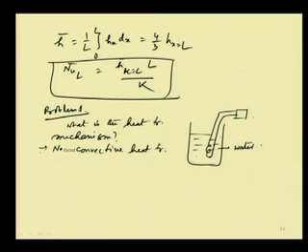Then what is there? Up to this layer, the fluid is heated up, and once the fluid heats up, it will go up and the other fluid will come down, so there is circulation. From the bottommost part of the coil to the top layer of the water in the bucket, in this region there will be free convection or natural convection, because the fluid will be heated up and go upward.